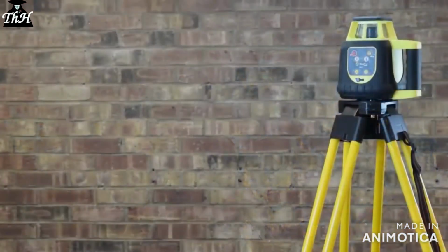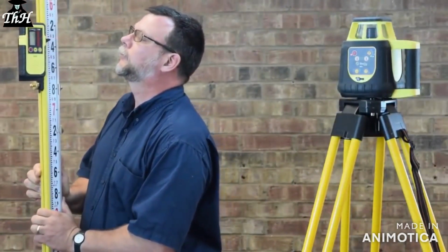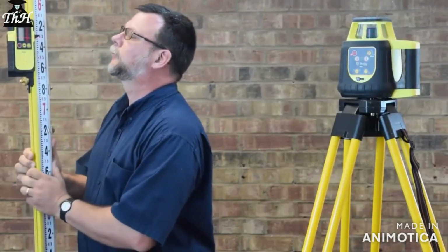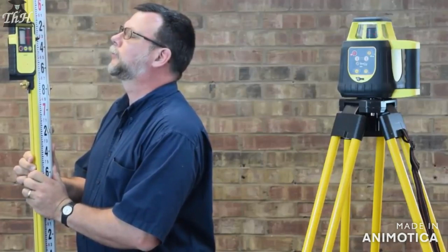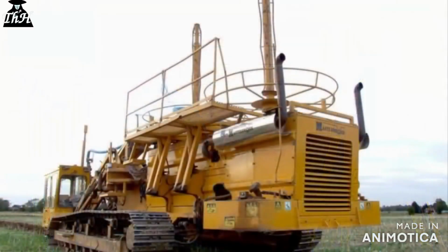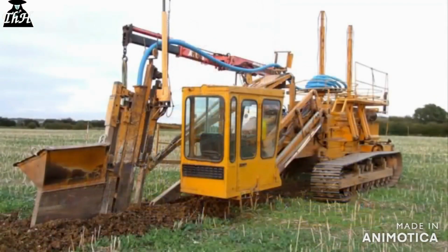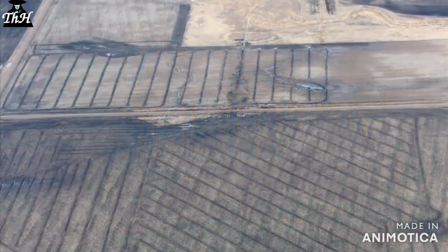With the advent of inexpensive laser devices, the rotary laser level has made some leveling surveys possible with only a single surveyor. A revolving mirror produces a horizontal plane of laser light. A laser detector on a special leveling rod enables measurement at each desired location. Farm drain tile installation equipment commonly uses a laser plane to control the pipe depth, ensuring proper slopes and efficient drainage.